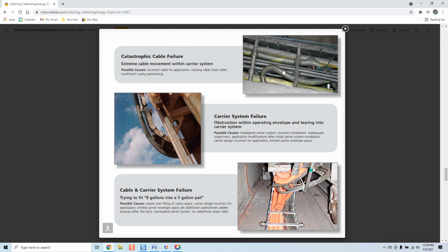Here's what they mean by the knotting effect. This is what you get until it finally breaks through. If it breaks through the PVC casing and you are using shielded cables, guys, you could potentially have a dead short on your hands and a cable fire and a meltdown. So very, very dangerous. Not typically seen, thank God, in our smaller systems, but definitely seen in larger systems.